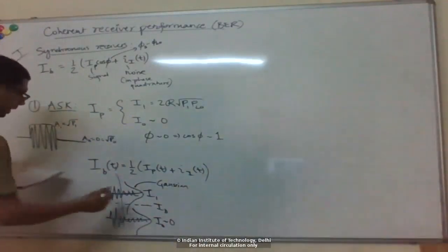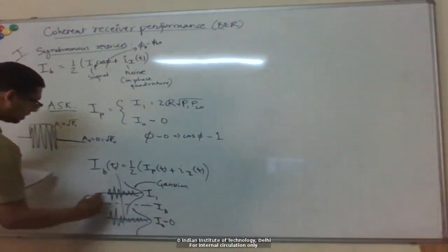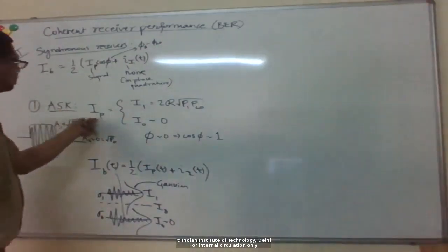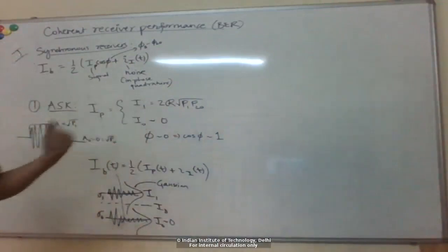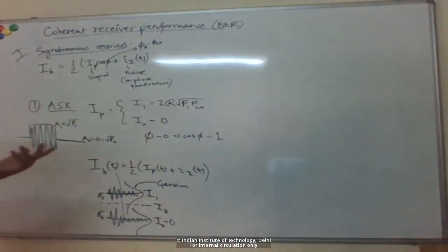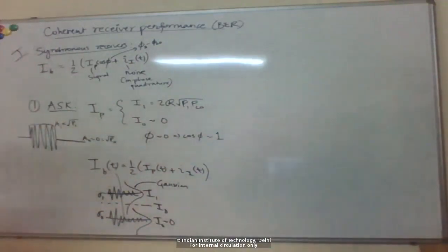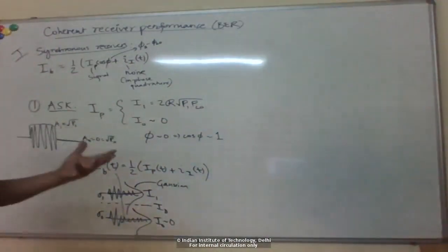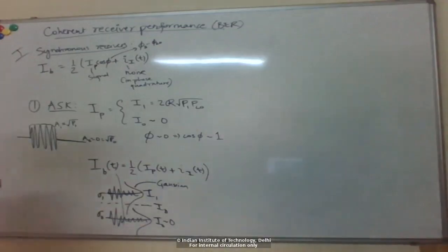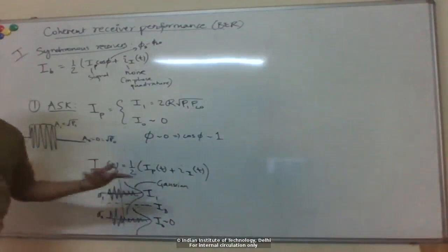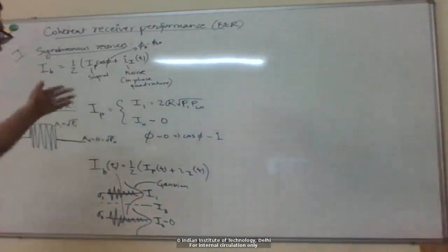Right, so again, you could take variance sigma, standard deviation sigma 1 for bit 1 and sigma 0 for bit 0 in just the general case. But here, because of the local oscillator, we go into the shot noise limit, right? In the shot noise limit, the shot noise is coming basically from only the local oscillator, because the local oscillator power is much higher than the received signal power. So both sigma 1 and sigma 0 will be the shot noise from the local oscillator for this case.